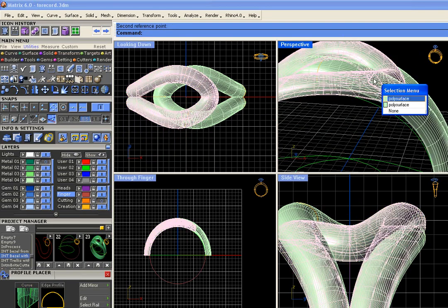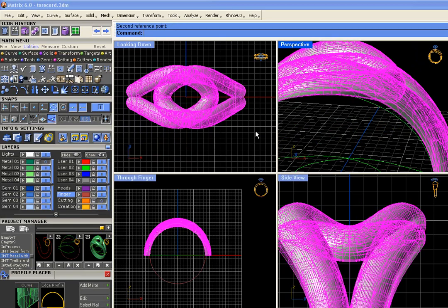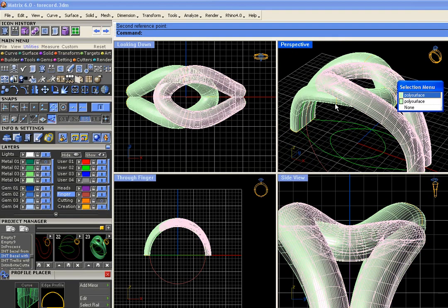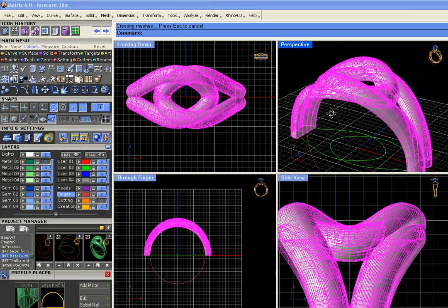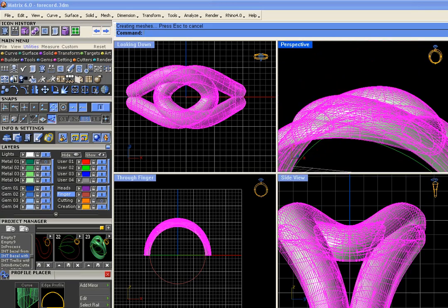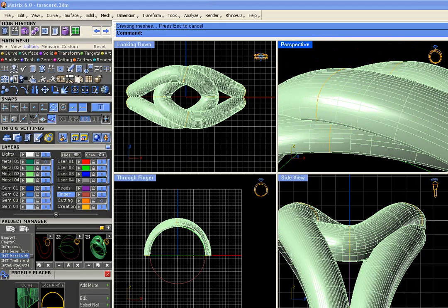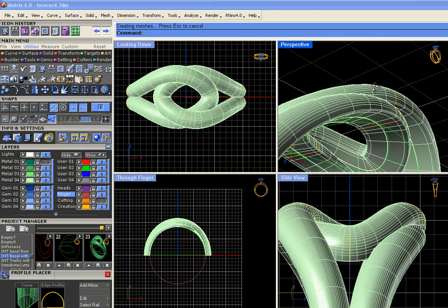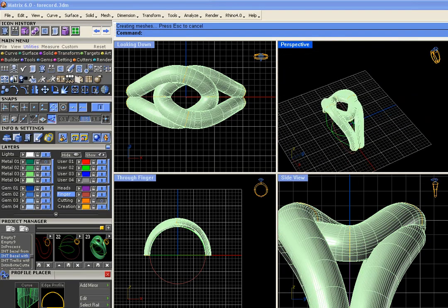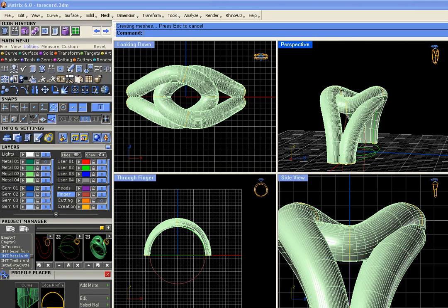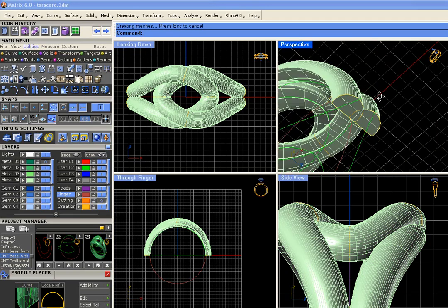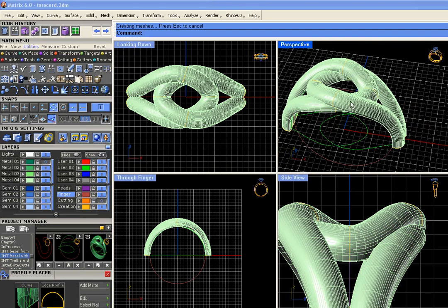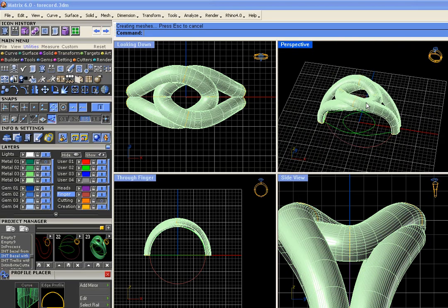And we still have the intersection problem up here. Okay, so we still have intersecting solids we need to fix. And this we can easily fix with Boolean union. So we're just going to take both of them and run the Boolean union command, and that's going to take care of the intersecting solids for us. So we have a single piece, and if we could look inside here with our x-ray vision, we wouldn't see any intersecting solids. Okay, it's doing in Boolean union what we just did manually at the side here, which is splitting the pieces with each other and throwing away all the intervening stuff. Okay? Boolean union can only handle the easy instances of those. You and I have to do the tricky ones.